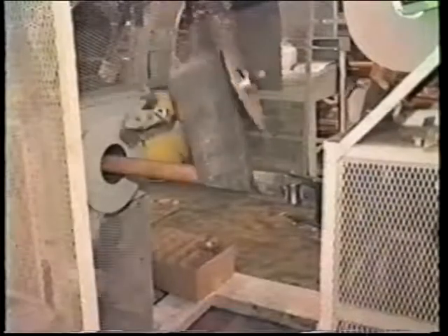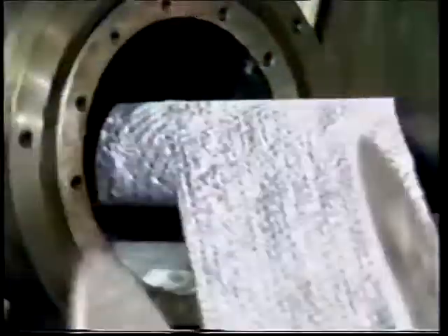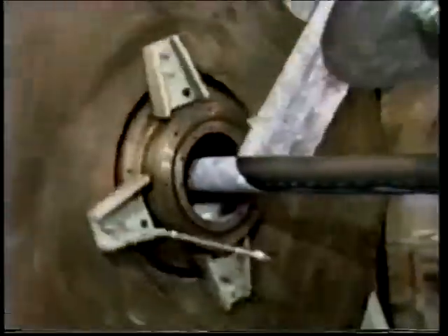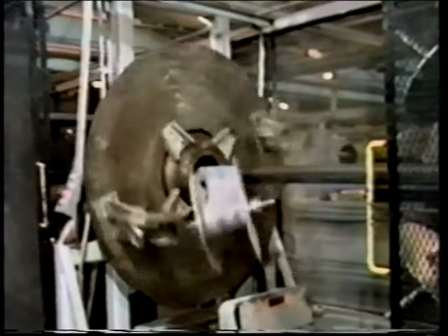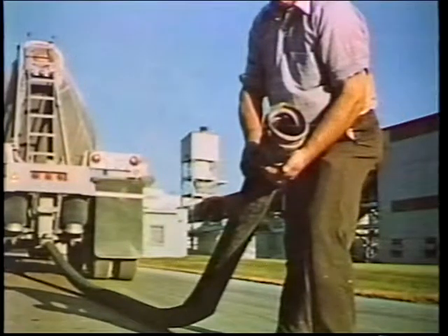Wrapped construction was the earliest form of manufacturing hose. It consists of layers or plies of fabric wrapped around a tube that is formed on and supported by a rigid mandrel or steel pole. A machine may be utilized to apply the layers of fabric. This method results in a hose for discharge applications in lengths up to 200 feet.